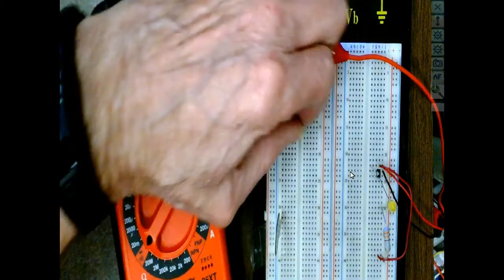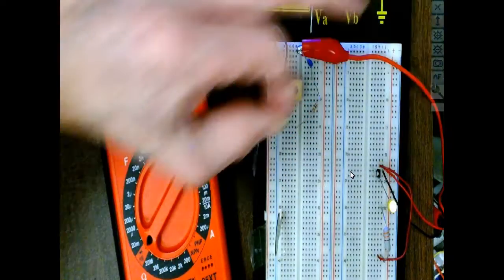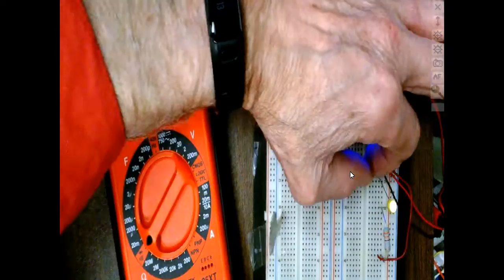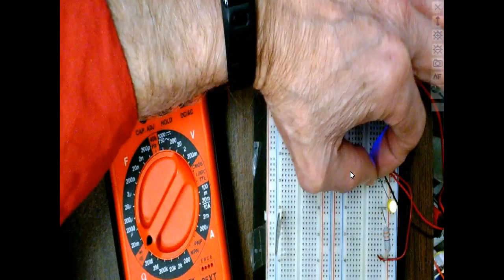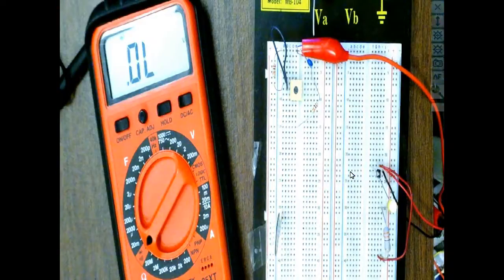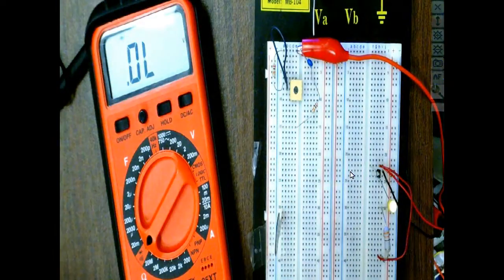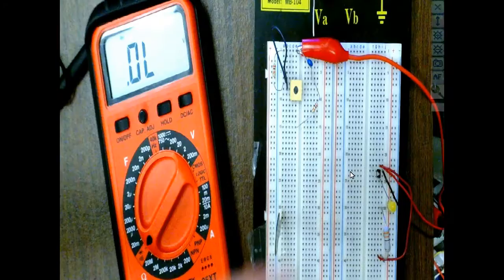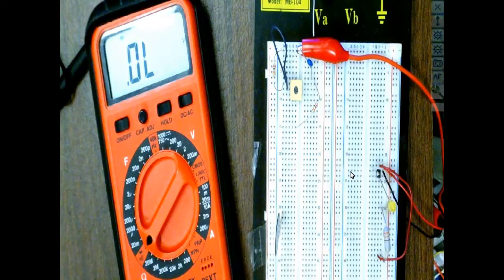All I'm going to do is bring my magnet up to the Hall effect sensor, and you see the light turned on. I can keep bringing the same polarity up there, and nothing happens. I'm going to turn the polarity around. Now I'm coming in with the opposite polarity, and when I get it close, the light turns off. And this is what we mean by latching Hall effect.